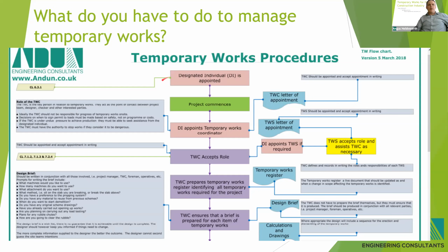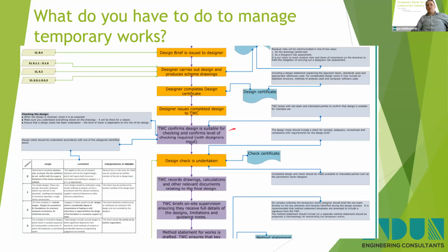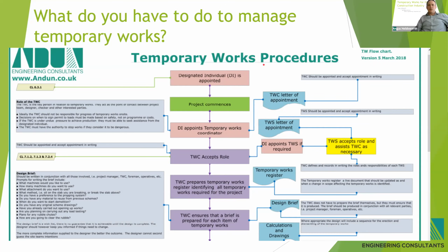It's generally going to be someone fairly senior of an engineering background who knows and understands temporary works. It's going to be a director of engineering or something along those lines. The DI will appoint everybody, so the TWC, temporary works coordinator, and the TWS, temporary works supervisor, who works and assists the TWC. On these bigger jobs, you can have a number of TWCs, but that kind of gets outside the scope of